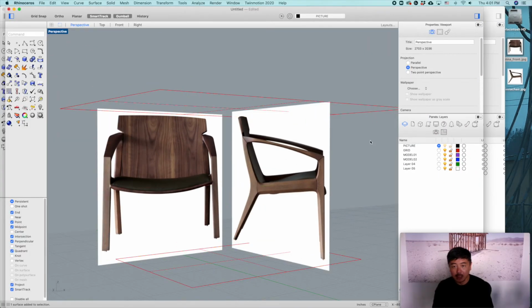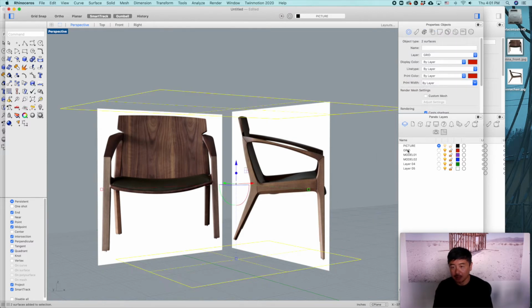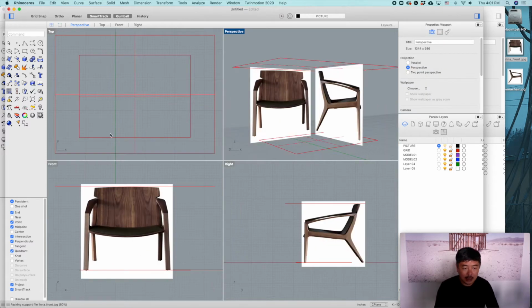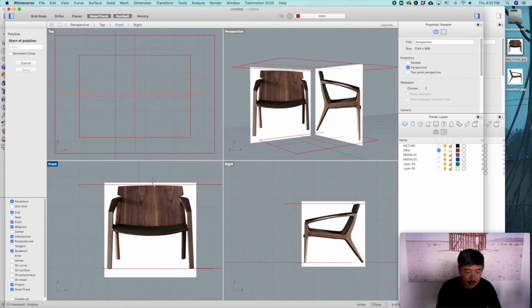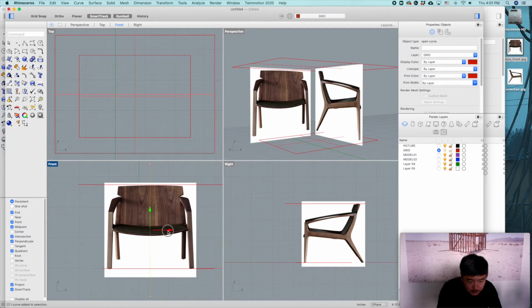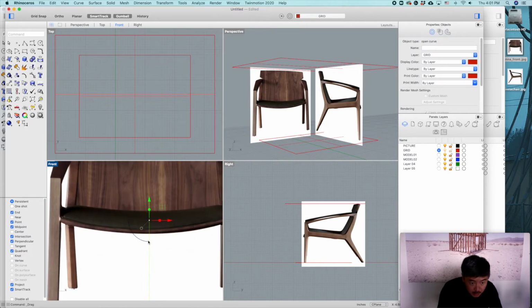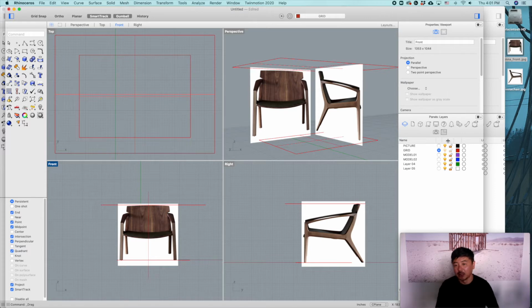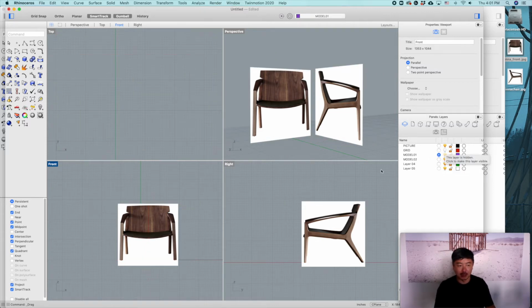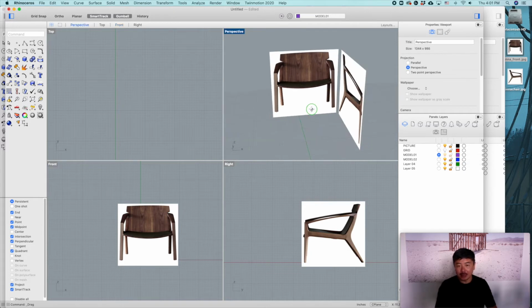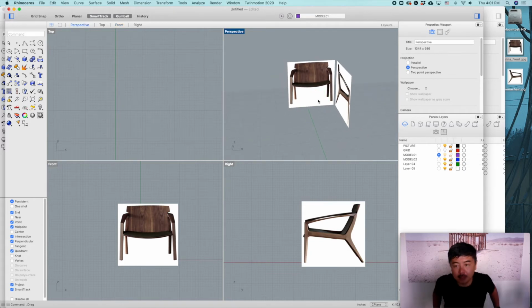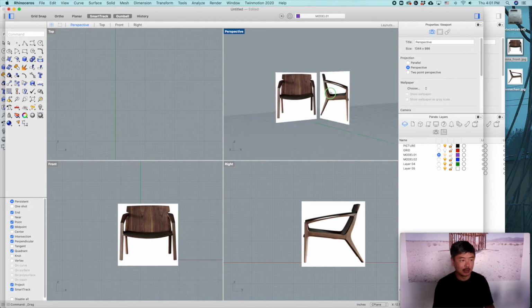Again, we can put these red grid ones into the grid layer. Another thing that I think we need is the center line on the grid layer. So you can activate the grid layer and then draw a center line. I think somewhere around here would be the center line, so that would be on the grid. For now, we don't really need to show the grid, so you can activate the model 1 layer and deactivate the grid layer. Okay, so that's the basic setup part that you need to get started.